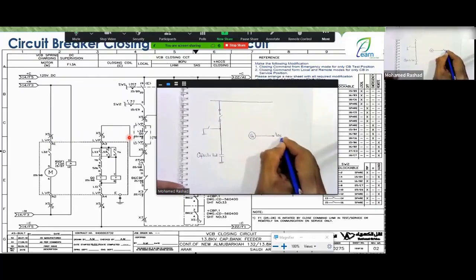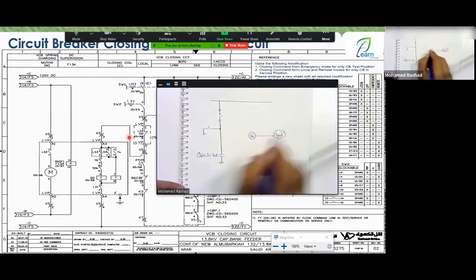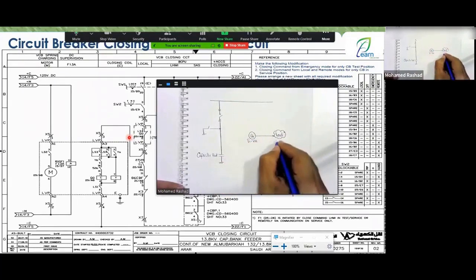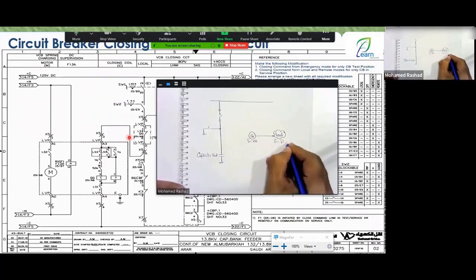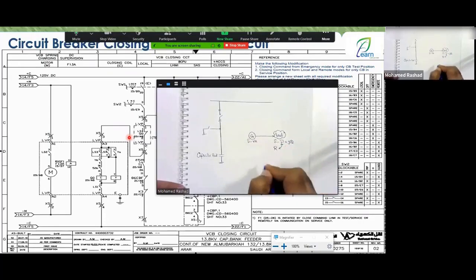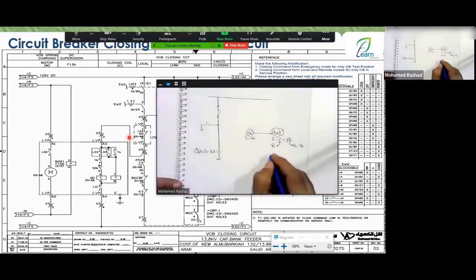All right, very good. This generator produces S, which is the apparent power in volt amperes. Consequently, this load also draws S, which consists of P plus jQ, correct? The P comes from any resistive load, and the Q comes from any inductive or capacitive load. All right, very good. In the end, you have the impedance of the load, which is R plus jXL minus jXC.